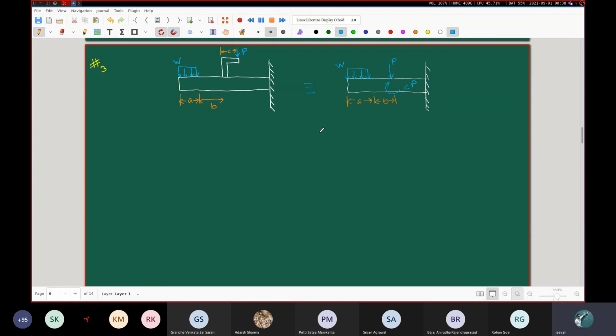Sir, in complicated things, if given cables and so on, we can directly consider the equilibrium of this cantilever. You isolate out the cantilever; it could be a simply supported beam also. So you separate out the beam and consider the various forces and moments that are acting directly on the beam as if no other thing is present.